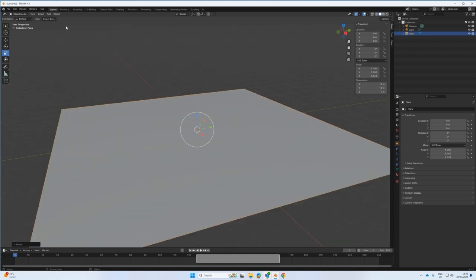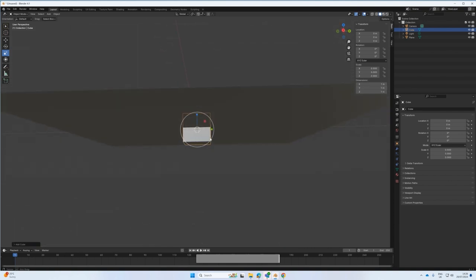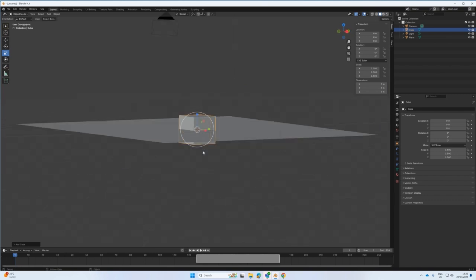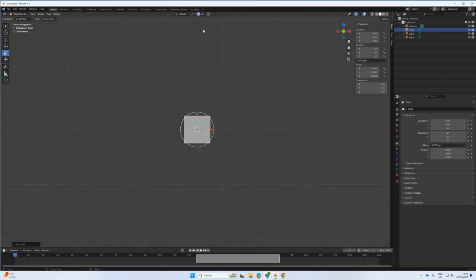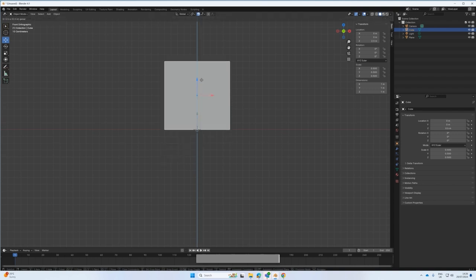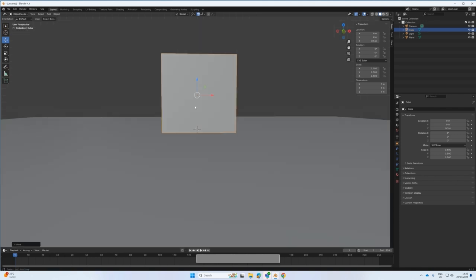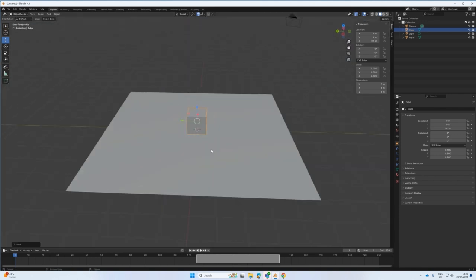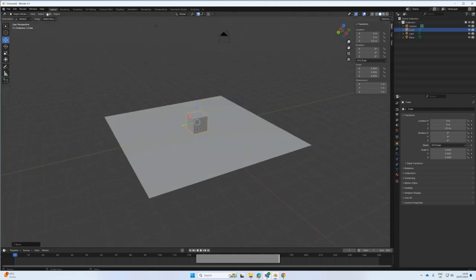Okay. So now I'm going to create my cube in the same place. Create a cube. Let's put 1 meter. Just select here and put 1 meter. So that's my cube. Now my cube is overlapping. So I can come here and using my snapping tool, press G to move. I can just bring it here and snap, and I know it's not snapped to the grid. It's on the floor here, so it's on top of the plane.